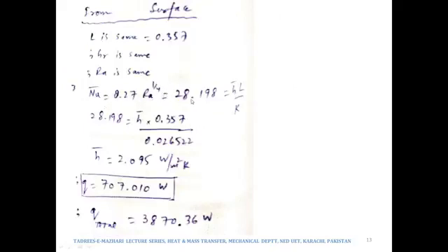So we get this Nusselt number as 28.198, and upon equating it again to the same ratio hL over k, we get the value of convection coefficient as 2, and if we put this value of convection coefficient in hAΔT, we get Q as 707. Upon summing up those 4 Qs, 2 from vertical sides, and 2 from horizontal sides, we get total heat transfer as 3870 watts.